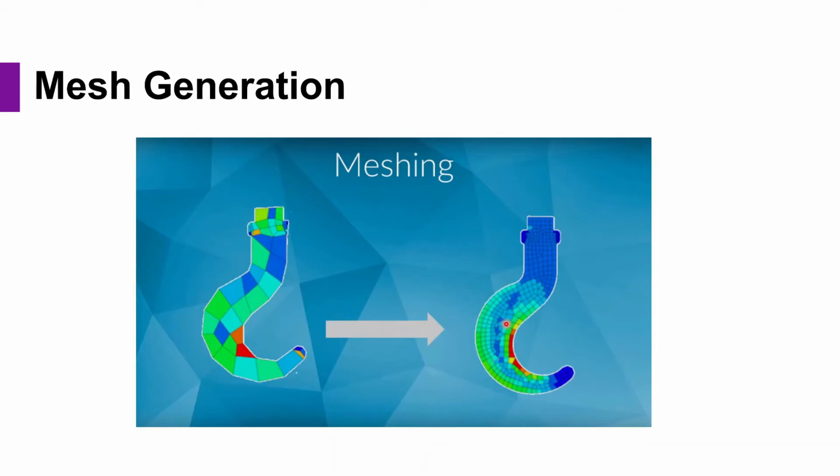Great. So the 1,000,000 will give you a much more accurate result because the number of the mesh helps me to apply those equations that I have to the different areas, which basically cover the majority of the area, all the area of the geometry that I have, so I will get a much more accurate result. How about if I increase that 1,000,000 to 10,000,000? How about 100,000,000?